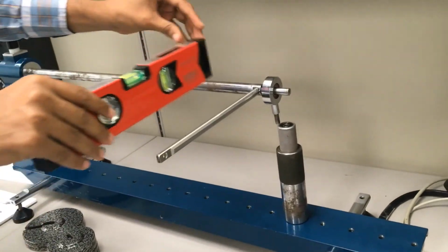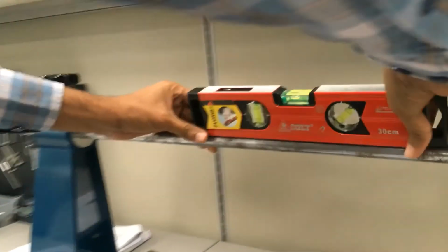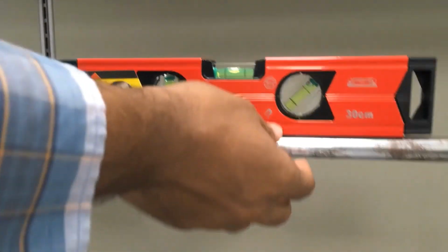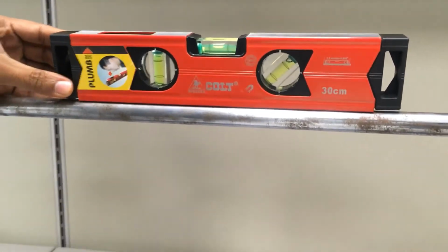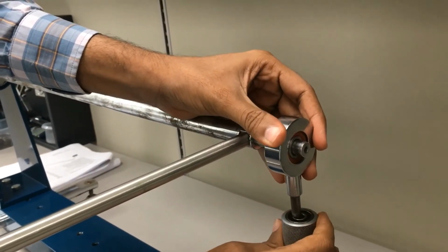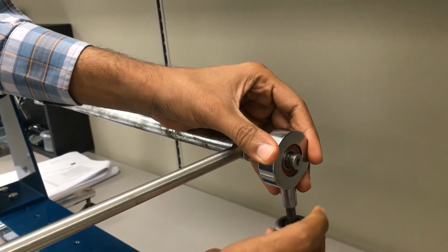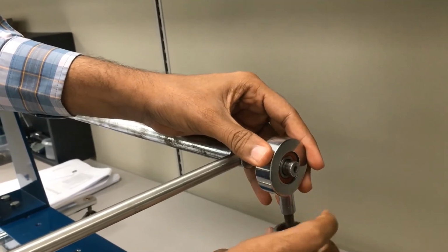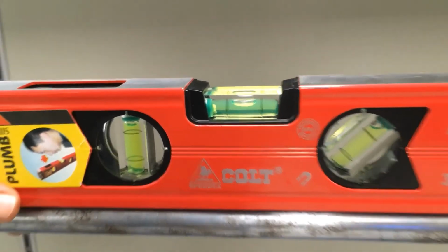So now the first level was in this plane. Now the other level will be in the other plane, which is very good now, but imagine that if I apply some load, you see the point is changing now, on the other side. So I need to fix it to have a horizontal leveling by rotating this. And I need to make sure that this is horizontal. Yes, this is perfect.